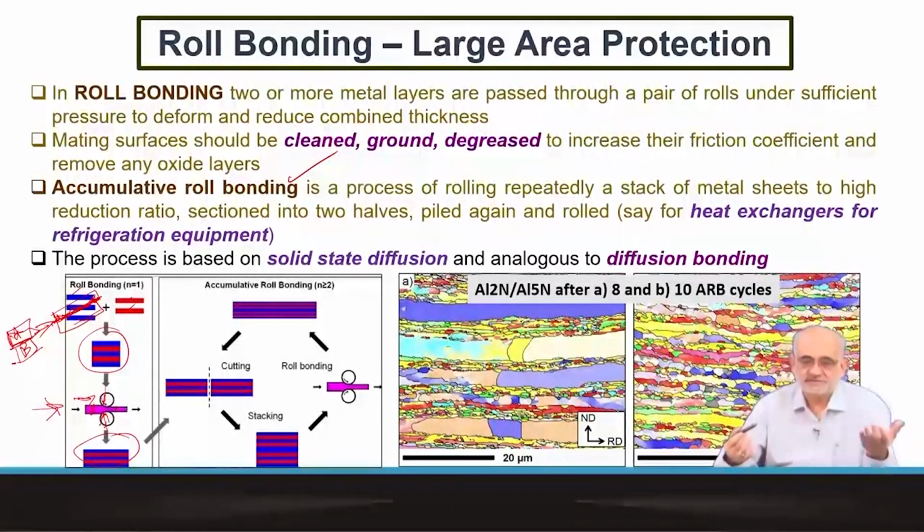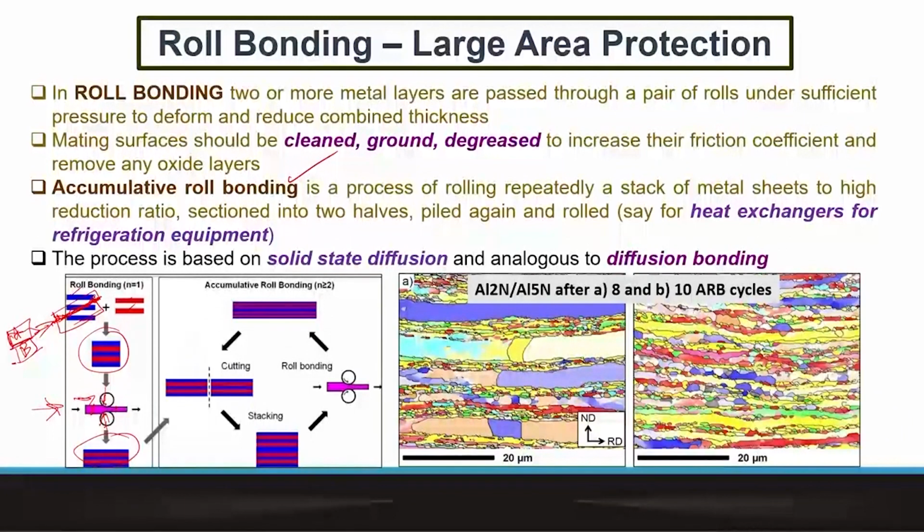When you subject a thin section to diffusional bonding processes, there is every possibility of surface corrugation or complete through and through penetration. In the process, the thin sheet can be rendered fairly brittle, which we don't want. So in such cases, we do roll bonding processes so that there is enough strength at the interface because of mechanical interdiffusion, but we also create very good surface protection.